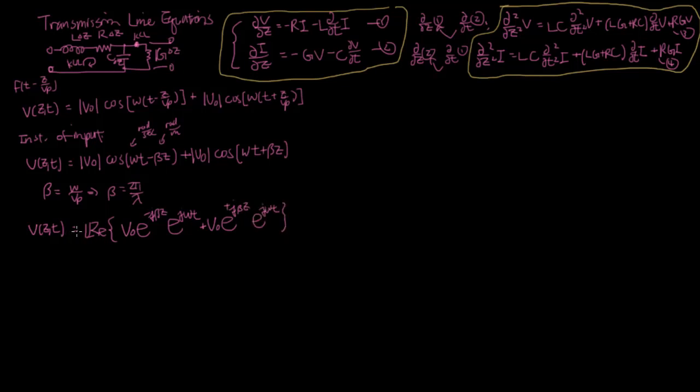So as a quick review, what we mean by phasor analysis is that we only focus on the complex amplitude. Here we forget about the e to the j omega t and taking of the real part, do our analysis, and then once we're all done, we convert back to the instantaneous form by multiplying it by e to the j omega t and taking the real part.